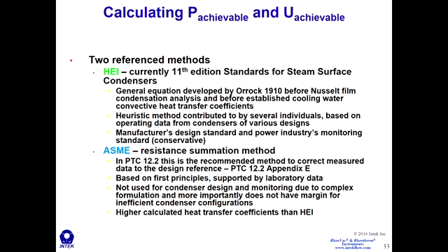It is the standard for conducting this test, and it's based on first principles. It's not an equation that condenser manufacturers have made. It matches well to data obtained on single tubes in laboratories, but it does not really accurately identify what you should expect from a condenser used in industry.